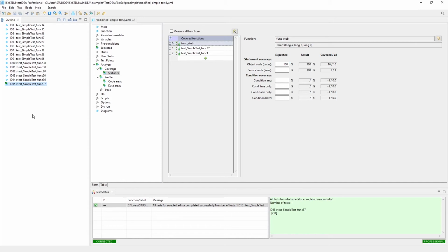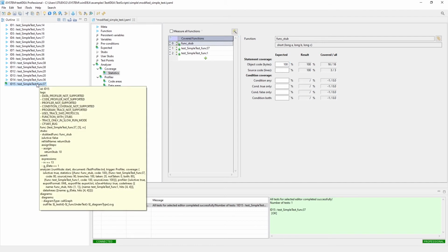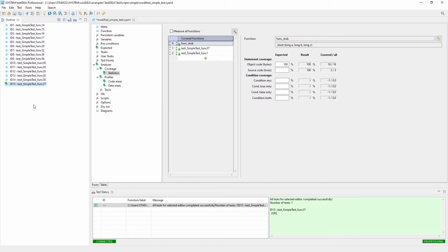But sometimes you just don't have a capability to use a hardware trace, and you can just let this run overnight. So using the slow run is definitely a viable option. Okay, so that's for gathering coverage. Obviously, slow run won't work for gathering any type of timing information because you're single stepping. That works fine for unit testing. You won't be able to get any real-time profiler information from the slow run feature.